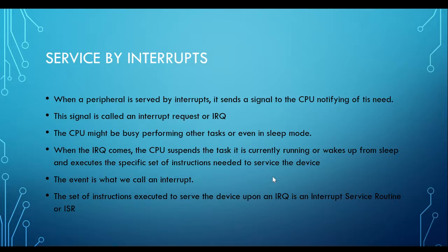Which is the interrupt service routine? It is the blinking of the LED, not the interrupt in the pin. The interrupt in the pin is called interrupt, but the blinking of the LED itself is called interrupt service routine. Now, I'm giving you some definitions, probably in tutorials or whatever. I'll bring up one of the codes and show you, well, this is what we call the interrupt. Which part is called interrupt service routine?